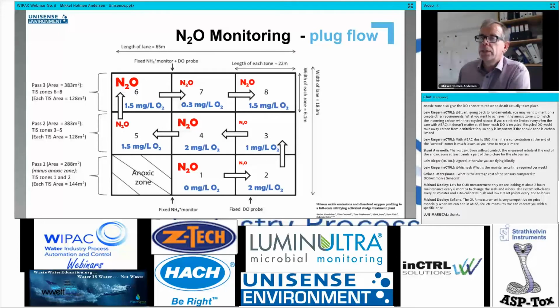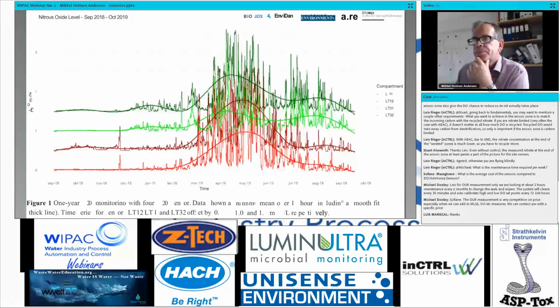Another thing that is really important is, I think the text comes up weird here, it looks different in the original. But here it's actually a full year monitoring of 4 parallel tanks at Biofos, one of the largest wastewater treatment plants in Denmark. And you can see the variation over the year, that it's really seasonal dependent. During the spring and summer months, we have high emissions of nitrous oxide, whereas during the wintertime it's less pronounced. This is not a general picture that we see.